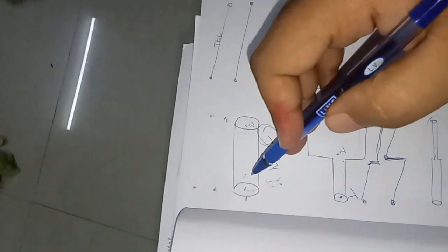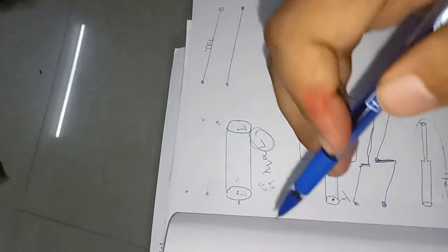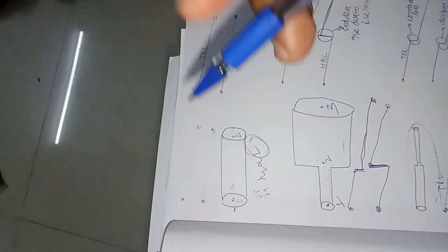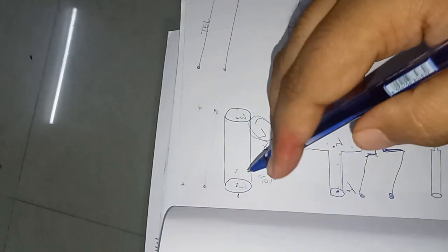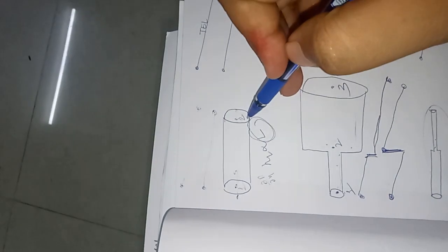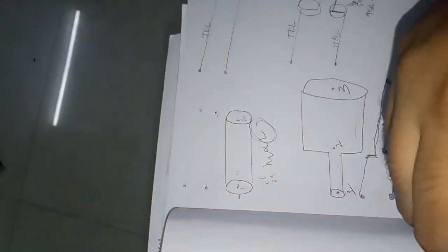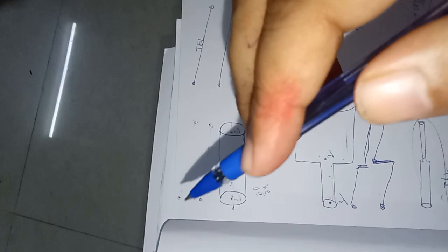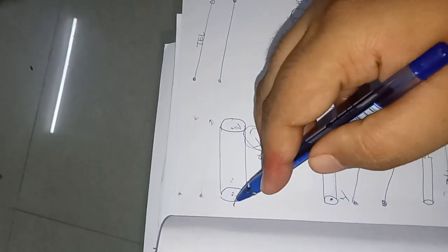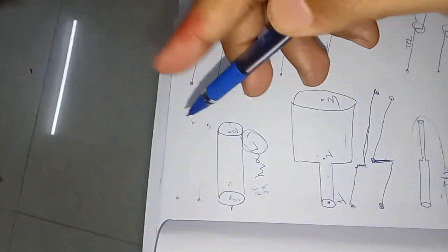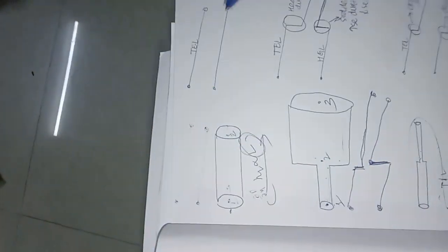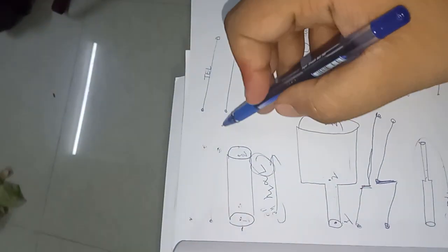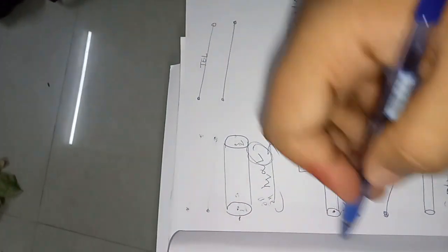This is the first case, in which there is a viscous flow in a pipe. First, drawing the hydraulic gradient line. As we go, pressure decreases linearly, dP by dx is equal to constant. So P by rho g plus Z1, as Z1 is constant, the hydraulic gradient line depends only on pressure, and as we go lengthwise, the pressure is decreasing. So the hydraulic gradient line decreases linearly.